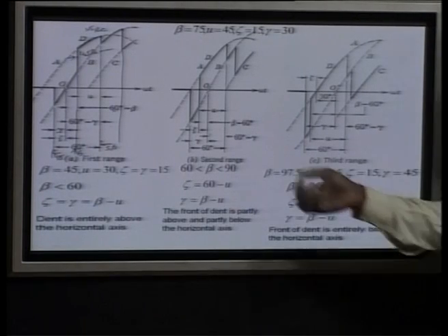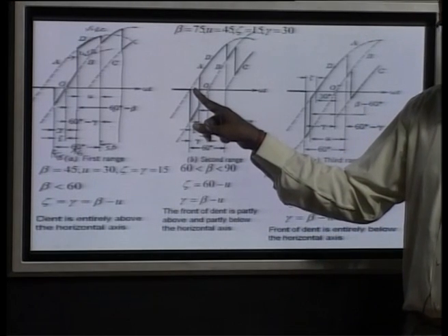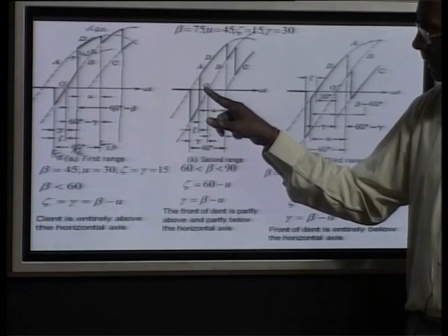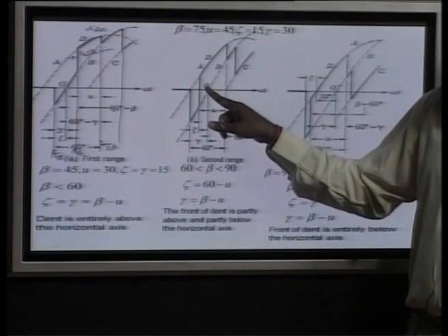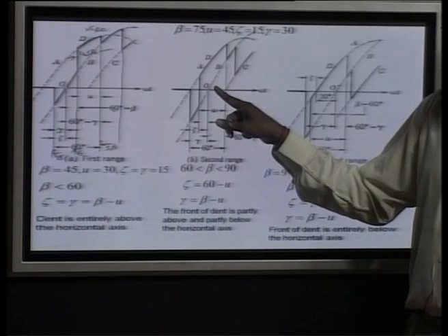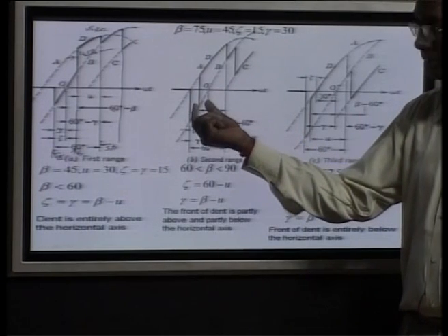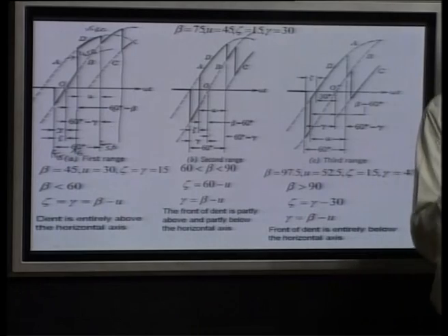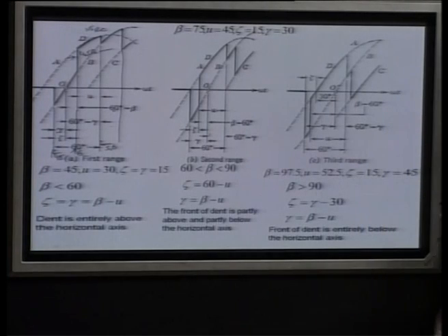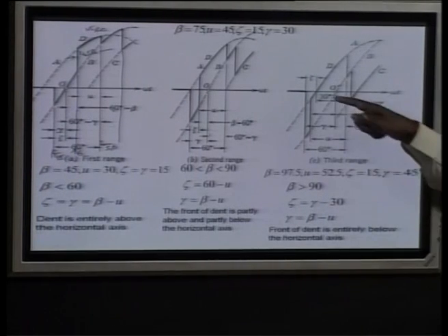As per our definition, this smaller portion is your zeta: the end of the conduction and then the non-sinusoidal reversal of the voltage. So, this is your zeta. But as a gamma definition, it is the end of conduction, then the sinusoidal voltage of the outgoing valve, the commutation valve. So, this is your gamma. Now you can say zeta is this much, and we have to maintain the zeta. What happens if zeta is not there? Now the voltage becomes positive, and again there is a possibility of commutation failure. Another possibility, if the beta is more than 90, this whole dent is coming below.